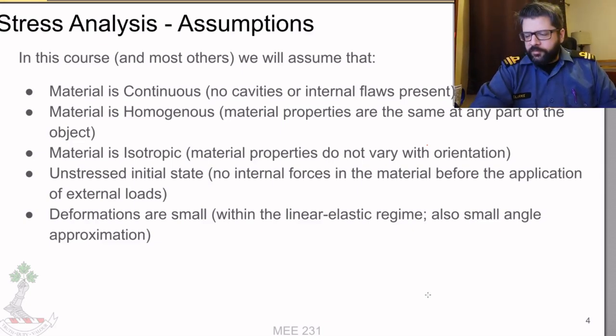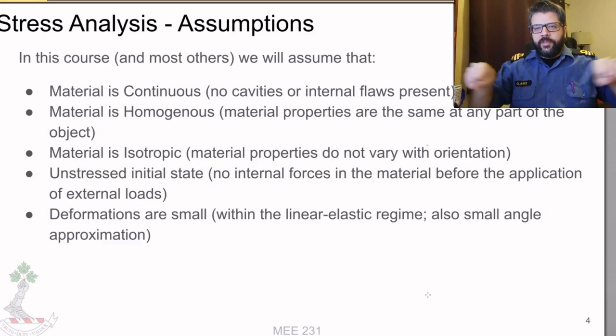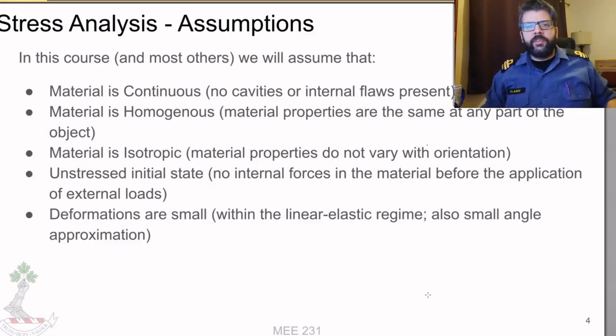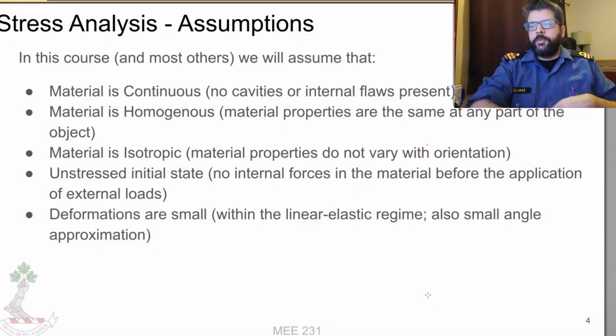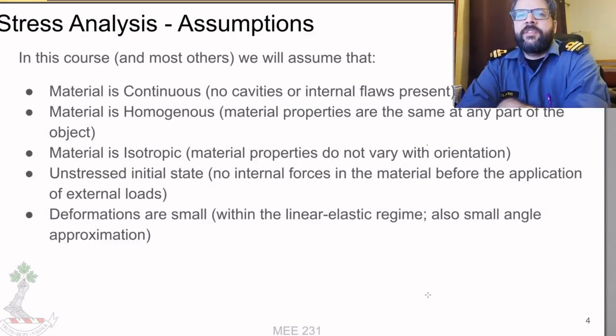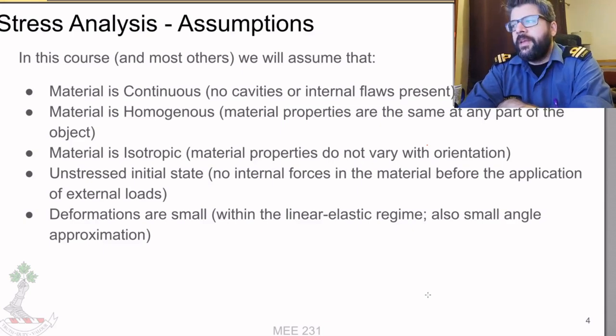The one that you're most likely to come up with this being a major issue is composite materials. Composite materials are very anisotropic. They are a lot stronger and stiffer if you pull them in the same direction as the reinforcing fibers are going than if you push or pull them in the opposite direction. Or sorry, in any perpendicular directions.